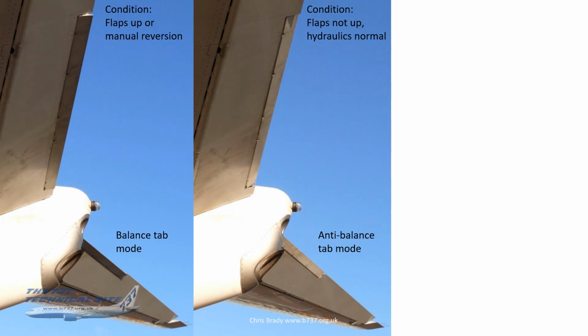Then what I did next was I got the FO, on the flight controls panel, to move the A system hydraulics to standby rudder, and see if you can guess what happened to the tabs when he did that. I'll give you a second. So what I'm saying is, with the flaps not up, hydraulics normal, as per picture 2, I got the FO to move the A switch on the flight controls panel to standby rudder.